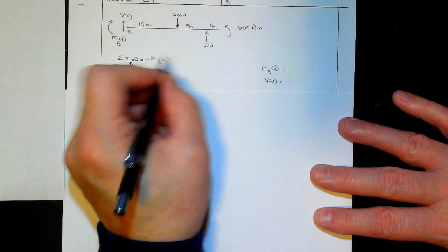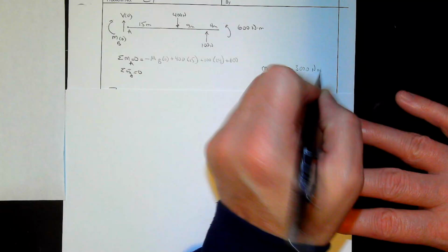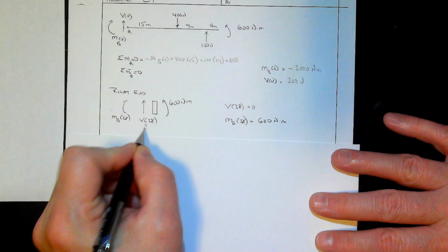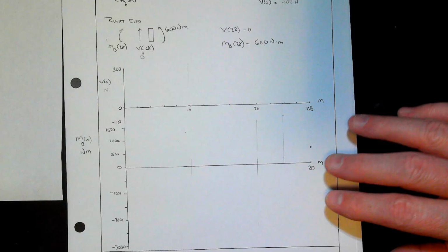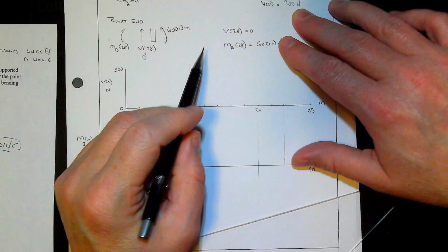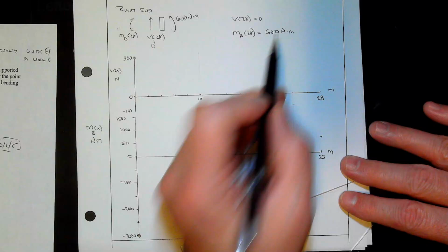We would go for the free body diagram. We take the wall away, and when we do that with a cantilever beam, we have a shear, so there's a force here, just like with a pin, and we draw the force in positive because that would be positive shear, but we must add the bending moment. The wall is providing a twist to keep this thing up. So we do that this way, where it's pinching the top, but we'd expect the beam will be coming down this way. So this will wind up being negative bending moment, but then the signs work out for us.